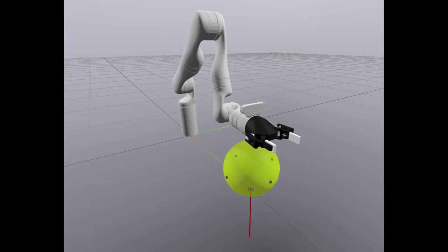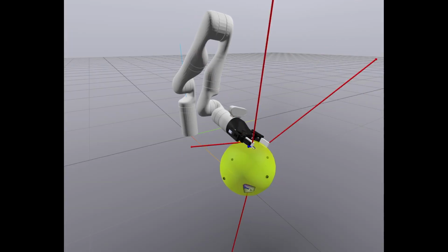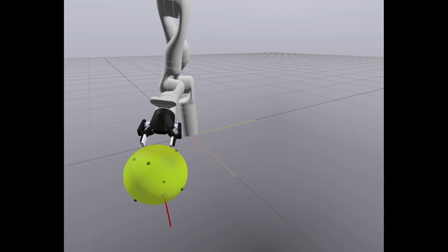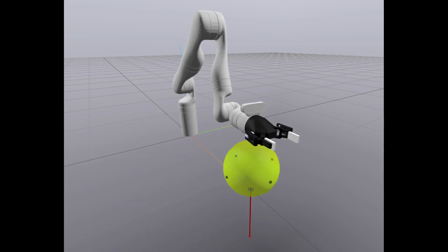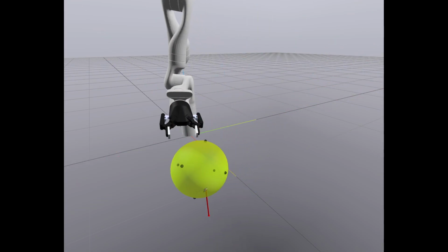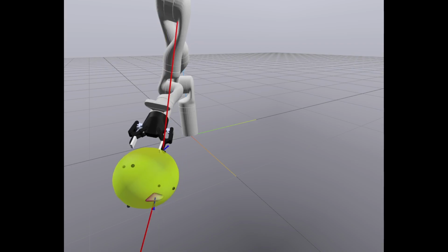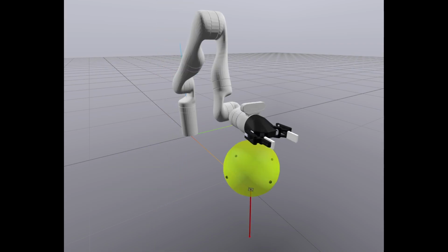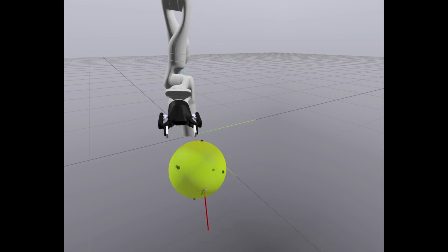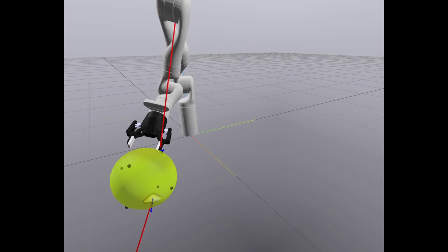We demonstrate end-to-end differentiation through contact using an out-of-the-box implementation of contact implicit iLQR using Drake. In our example, a Kinova Gen 3 robot arm efficiently plans a trajectory to move a ball to a target position on a plane without predefining the contact sequence. Our hybrid approach uses automatic differentiation through the geometry engine and propagates gradients analytically to reuse factorizations from contact resolution.